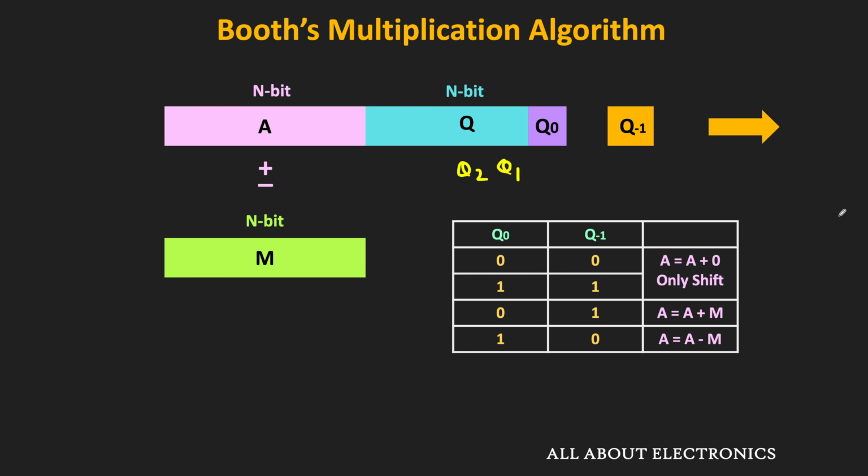In the earlier case of the add and shift method, we were doing a logical shift operation. After each right shift operation, the next pair of bits in the multiplier is checked. In this method, whenever there are multiple ones or zeros in the multiplier, there is no need to perform the arithmetic operation, and in this way we can reduce the time required for the multiplication.